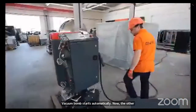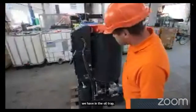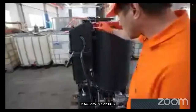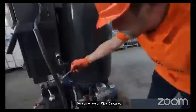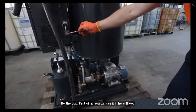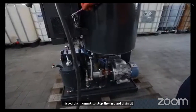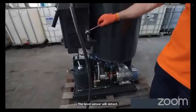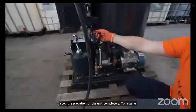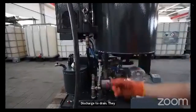Now, the other sensor we have is in the oil trap. If for some reason oil is captured by the trap, first of all you can see it in here. If you missed this moment to stop the unit and drain oil, the level sensor will detect the presence of oil and stop the operation of the unit completely. To resume the operation, you need to discharge, to drain the captured oil from the oil trap.